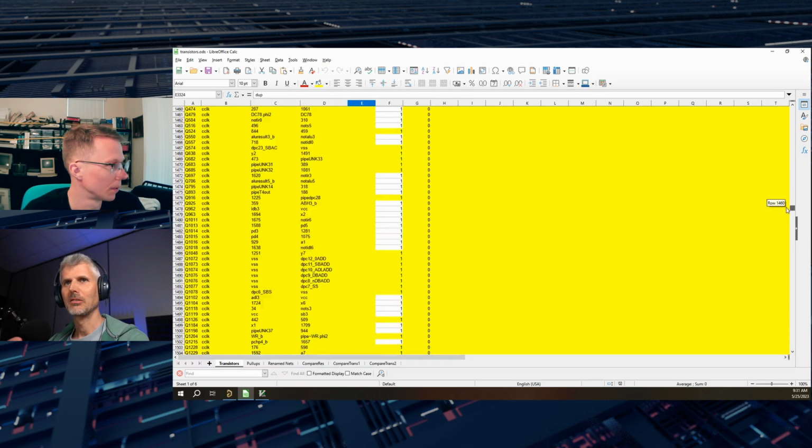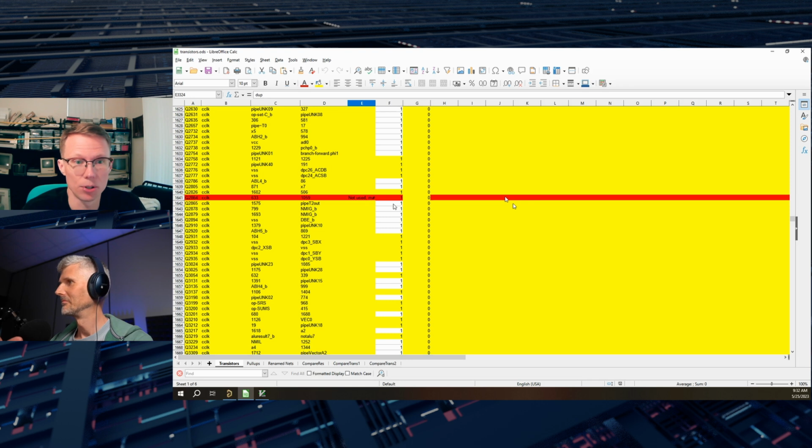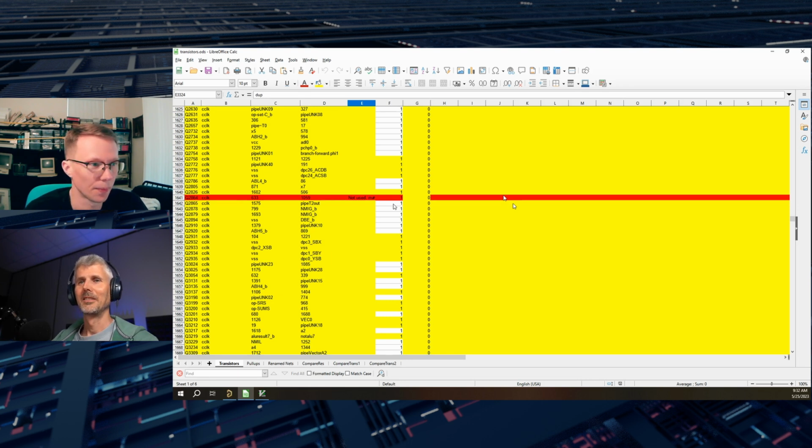The transistors you were using already were ESD protected then? Well, they either had built-in ESD protection, or I also added some actual discrete diodes to clamp the voltages on the pins to either VCC or ground, as kind of the typical approach that you would see on a discrete circuit board. Yeah.